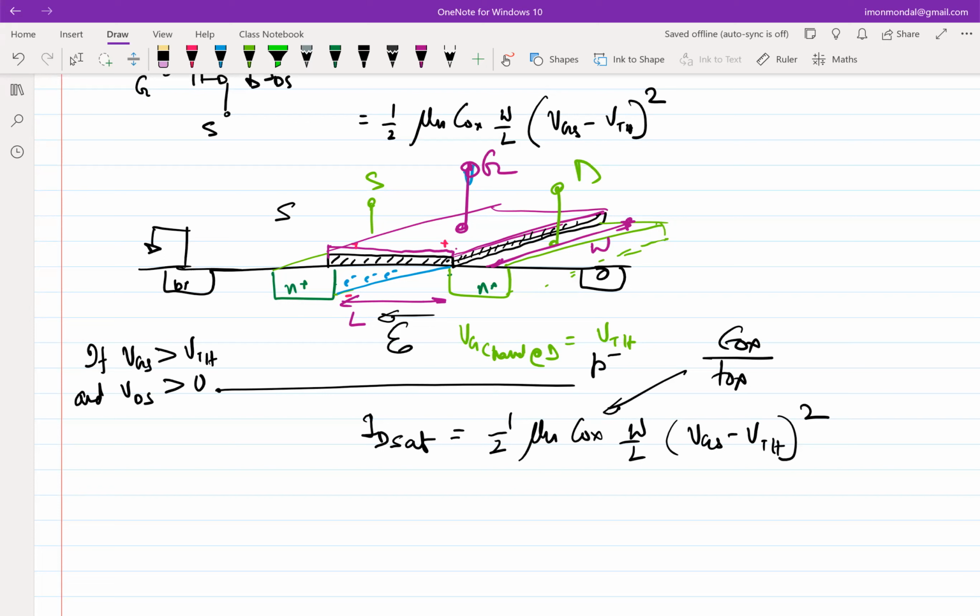You can influence the current in your circuit by designing appropriately and sizing W's and L's appropriately. But you have to be careful. Once you fix it, you cannot change it. That's not true for gate to source voltages. You can keep on changing it even during testing or in the lab. So W and L are also design variables, but these are one-time design variables.